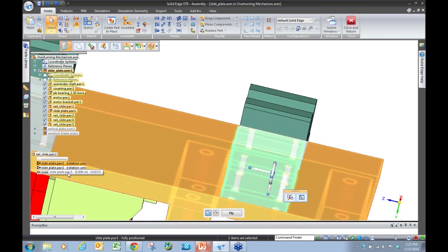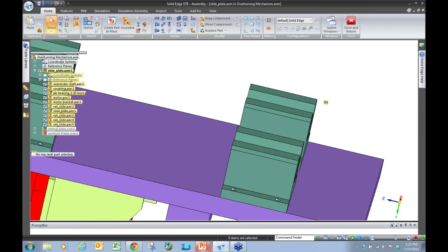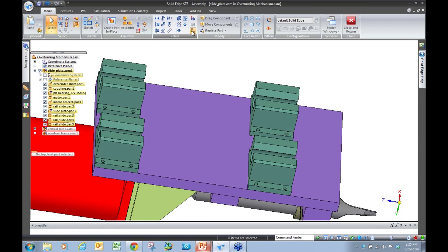So this is how we do that. We'll go here and select this part. We're going to use these relationships, and for now we're going to just suppress them. By suppress I mean I'm not going to quite delete them, I'm just going to turn the switch off. That way they're not applicable at the moment. So let me hit escape here.